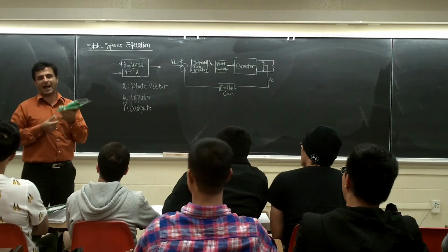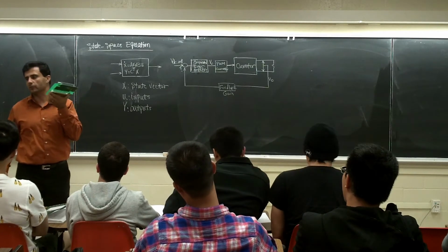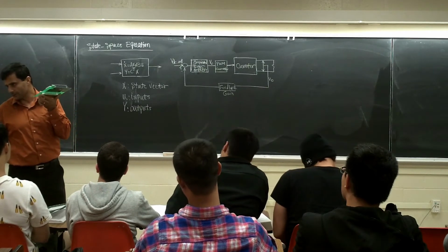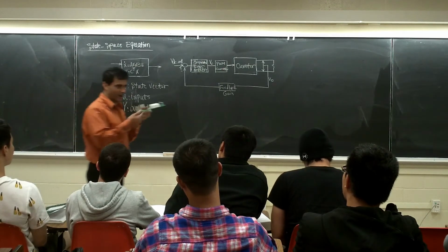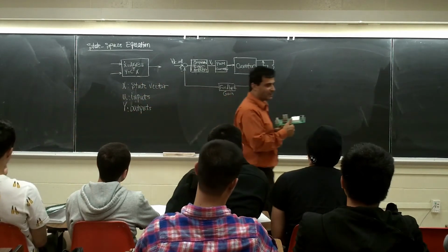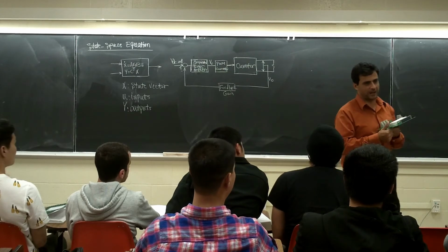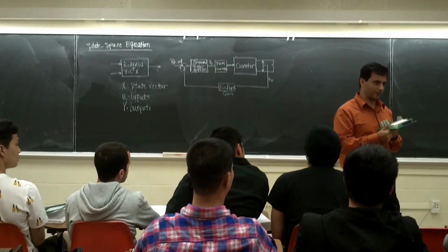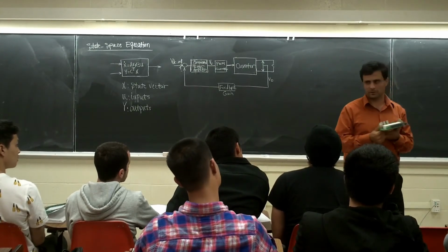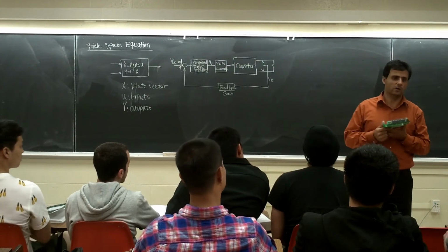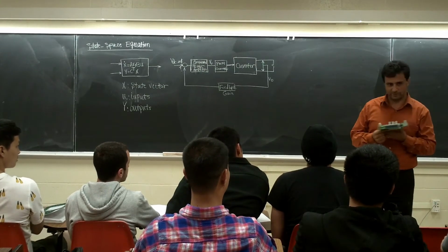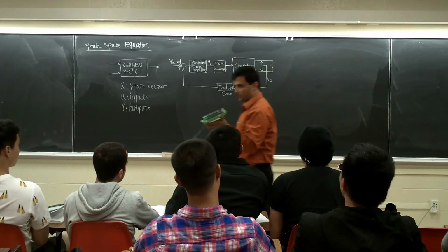Usually when there's 100 amps, the rule of thumb is just use it for 50 amps maximum. You know what I'm saying? For example, if I want to design this circuit, I say the maximum value I can pass through this module is 50 amps maximum. How much is the RMS, divided by square root of 2? Let's say 25 amps RMS. So I can have 25 amps RMS.